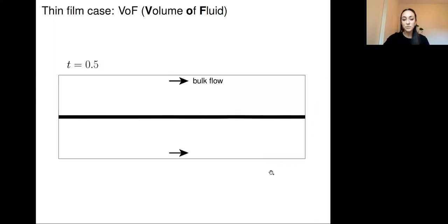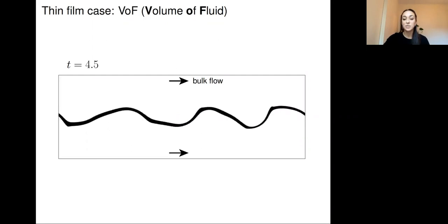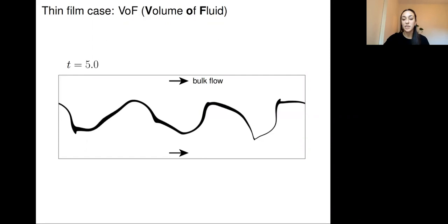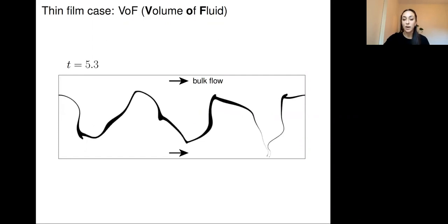We have it deforming, really not, we can't even discern it at the beginning, but in time these deformations grow and amplify slowly at first, and then really accelerating, if we see now in the next couple of time steps, very fast now, the film is really getting torn apart by those shear flows. And we see we have all sorts of things happening. We have thickening here. We have these little lobes, which cause big disturbances to the flow locally. And we also, as we'll see in a moment, have flow reversals. And here's where we stop the simulation. So as I said before, we're interested in the primary atomization phase.